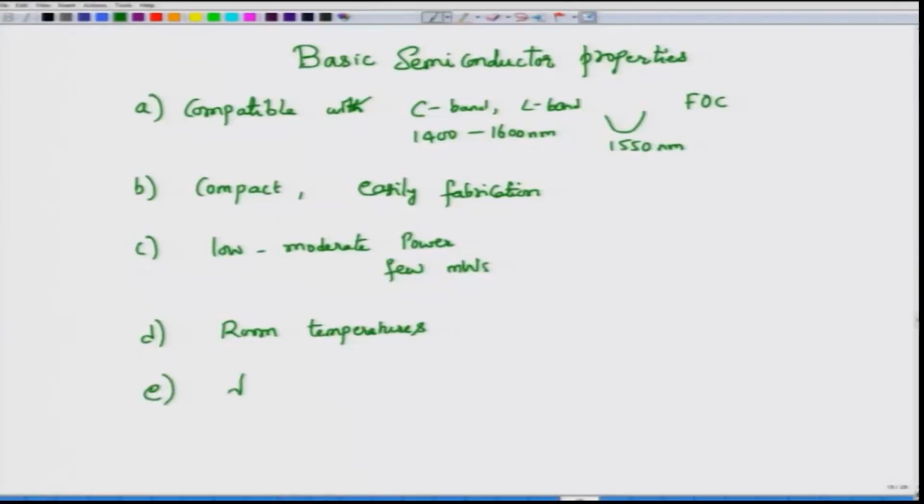So, it was very fortunate that in around 1969 or 1970, both low loss fibers as well as semiconductor diode lasers, which were operated at room temperature, therefore, they did not require a lot of current, and that is another advantage which I did not mention here. So, the drive current requirement is not too high. Drive currents of about 50 to 100 milliamps is sufficient for most laser diodes to start lasing and producing light output.